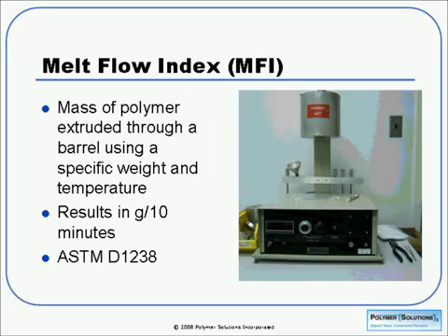It's roughly related to molecular weight and viscosity, but it is a single-point measurement, so it can be misleading at times. But it is good to determine lot-to-lot variations and that sort of thing, and it can be used in line with processing. So in that case, it can be quite popular. There's an ASTM standard, again, D1238, and this is something that you might commonly see on spec sheets or technical data sheets.